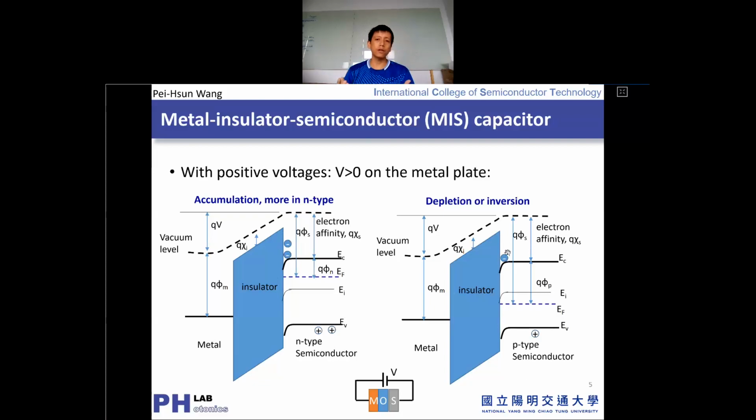However, for the P-type system, as long as we get a strong field, a stronger voltage applied on the metal, we still get a potential for generating the negative charge or electron along the surface. So you can think that the Fermi level apparently initially sits below the intrinsic level. That means you get more hole concentration. But later on, with the applied voltage, the Fermi level is still constant because, as we mentioned, it is just like a sea level.